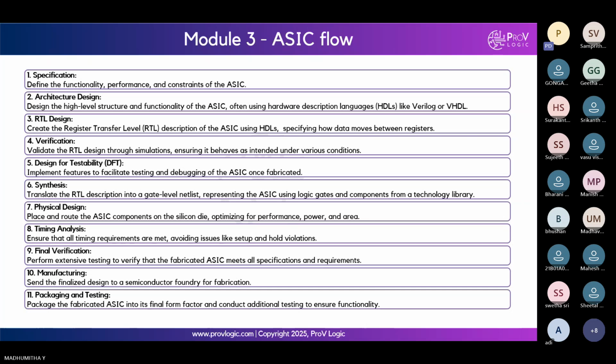Okay. So now I will explain what is point number 6. Point number 6 is called synthesis. In the synthesis process, now we will have the RTL, right? RTL design engineers have written the code, they have verified the code, and the DFT patterns are also generated by the DFT team. So now in the synthesis part, we will be generating one file called the gate level netlist.